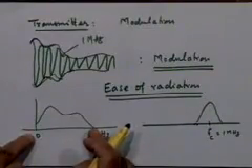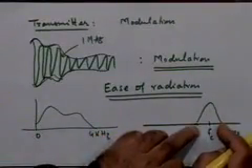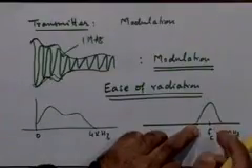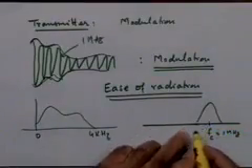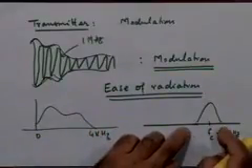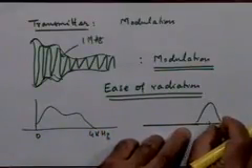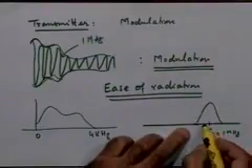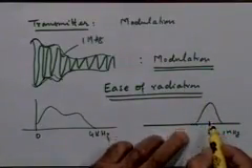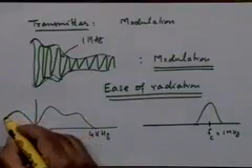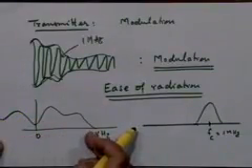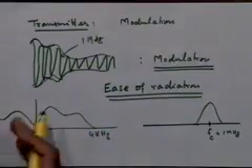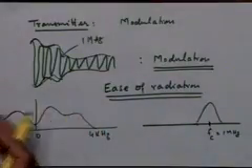Let me go back to this picture that I had some time ago. This bandwidth is 4 kilohertz. This bandwidth at the moment becomes 8 kilohertz, but the more important thing is not that; it's 4 kilohertz this way and 4 kilohertz this way. We'll study the nature of this signal later, but if you count both positive and negative frequencies, even this signal has 8 kilohertz bandwidth. Of course, that 4 kilohertz is imaginary, this negative.